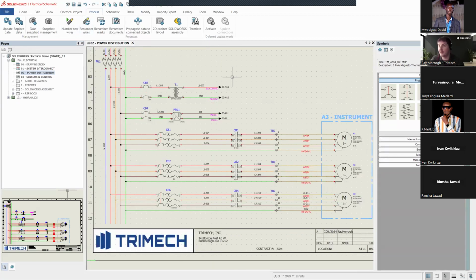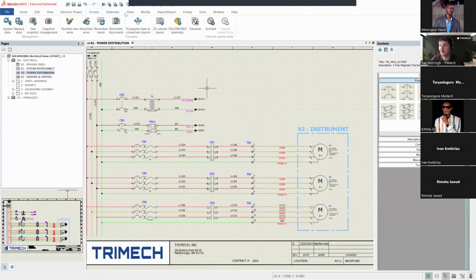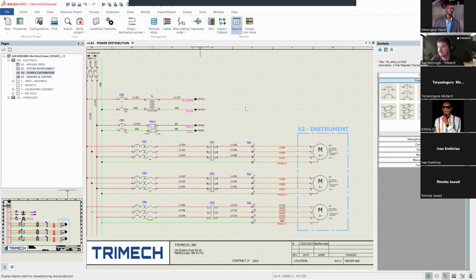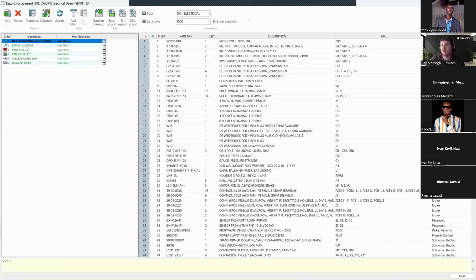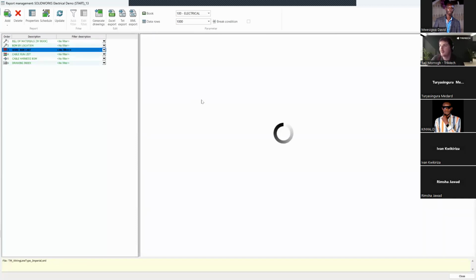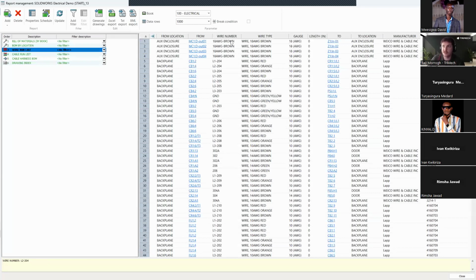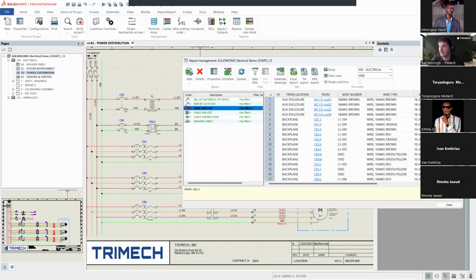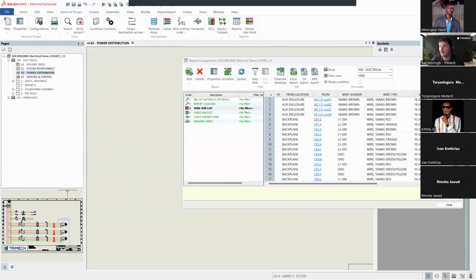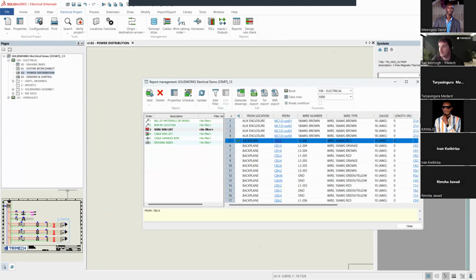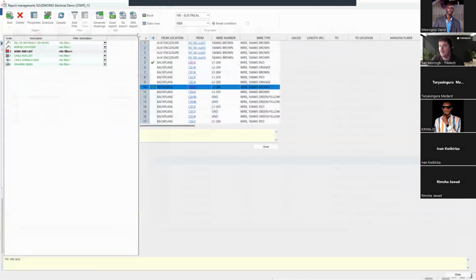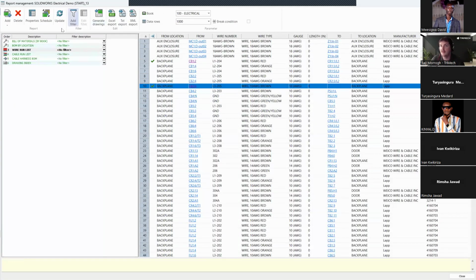And the reason we want to number those wires is because when we go to our reports page and we do a wire run list, all those wire numbers are going to be generated in our reports with links of where things are running to and from. This is pretty cool. So I'll show you like circuit breaker 1. If I click on it, just like with my wire run list, it'll take me to that location in the project, or, you know, let's do CV2 or something. It will take me there. And then if there's any changes here too, we can update it.